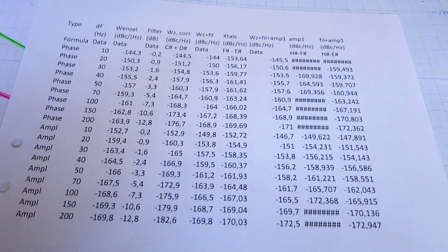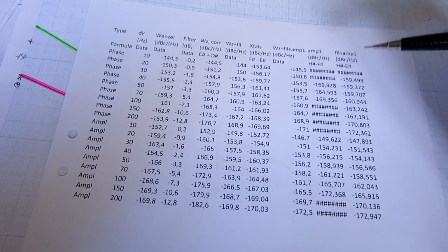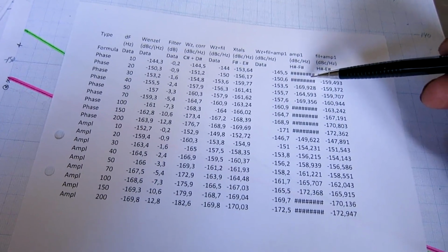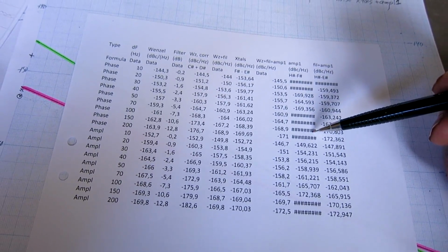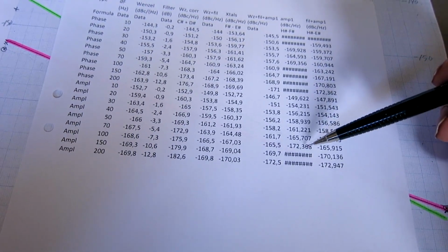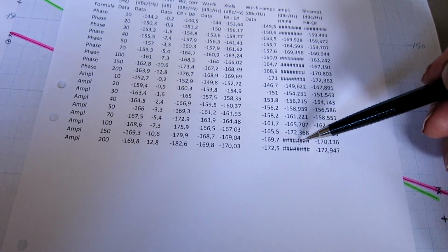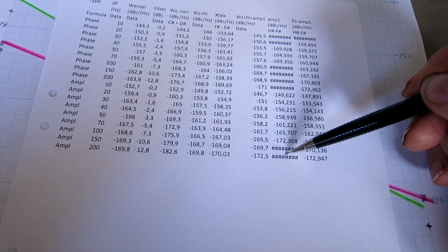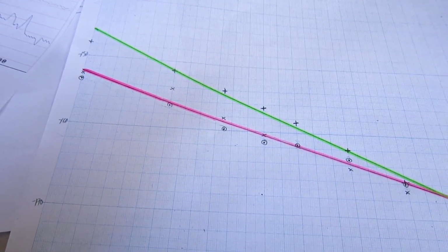Here is the evaluation of the spectra that I have saved. And the phase noise, the difference when adding the amplifier is too small to give any reasonable result. For the phase noise, I do get results at close separations, but at the widest the difference is too small. I get negative values here. Plotting them on paper, this is what I see.